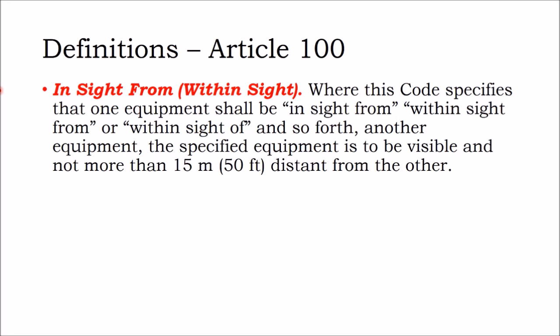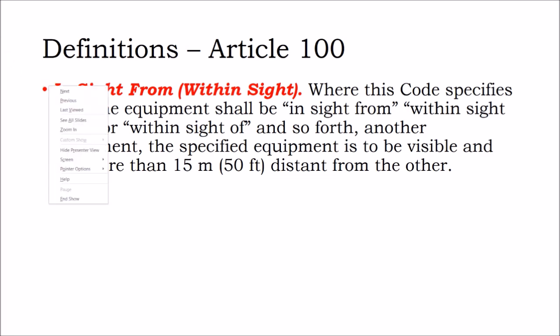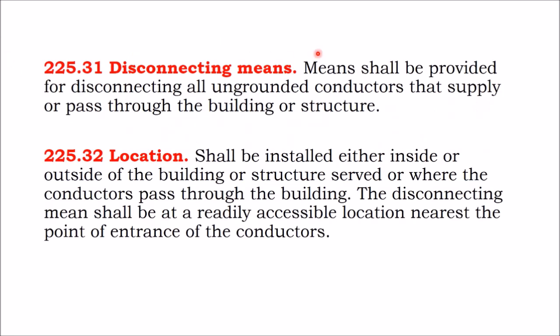But, again, when it comes to minimizing disconnect switches, you have to think about it in terms of serviceability. Just because you're not required to have a disconnect at the edge of the array doesn't mean that you shouldn't have a disconnect at the edge of the array, in terms of a serviceability point. Then again, you don't want to do overkill, because every time you splice a cable, you put more resistance into the system.